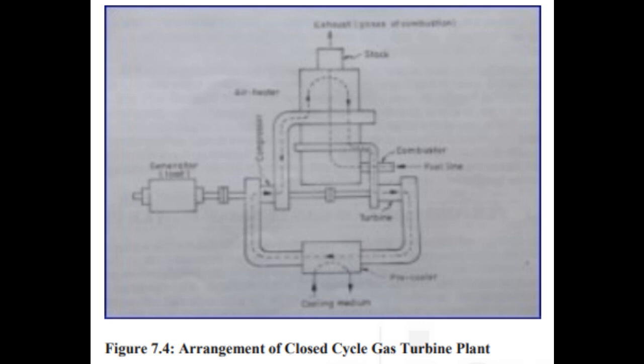7.5 Closed cycle gas turbine power plant and its characteristics. In the closed cycle, a constant quantity of air, or another suitable gas used as the working medium, circulates through the cycle over and over again. Combustion products do not come in contact with the working fluid and thus remain clean. A development in the basic gas turbine cycle is the use of the closed cycle, which permits a great deal of flexibility in the use of fuels. Moreover, the working medium of the plant could be any suitable substance other than air, which would give higher efficiency.